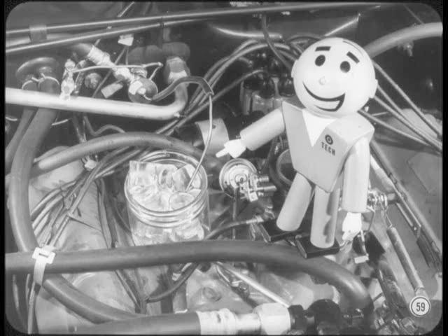Great. But how do I tell which one's the cause? You can put the expansion valve thermal bulb in ice water to test the valve. If the suction pressure drops, the valve's okay, and you know there's too much refrigerant in the system.